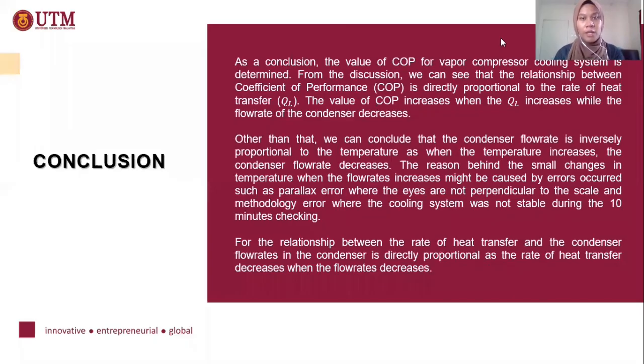That's all from me. As a conclusion, the value of COP for the vapor compression cooling system is determined. From the discussion, we can see that the coefficient of performance, COP, is directly proportional to the rate of heat transfer, QL. The value of COP increases when QL increases, while the flow rate of the condenser decreases. Other than that, we can conclude that the condenser flow rate is inversely proportional to the temperature, as when temperature increases, the condenser flow rate decreases.